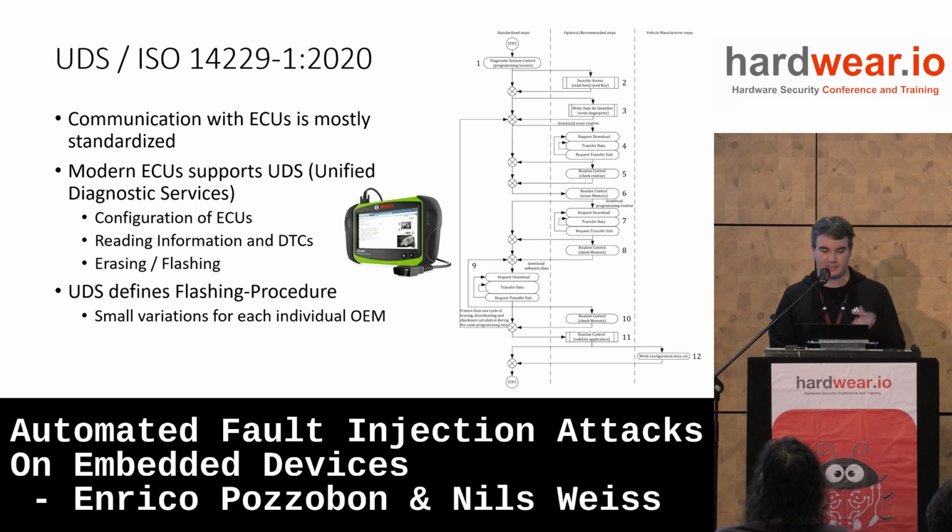It standardizes the communication between the ECU and the repair shop tester and how the flashing procedure is done. So it defines the update process for automotive ECUs. And I will go quickly into how this works.